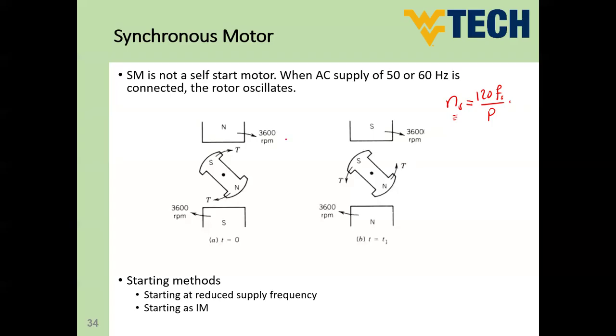If you imagine with me now in this figure, I'm going to assume that you have a pole when we supply the motor at one time, let's say at t equals 0. The pole on this side is N and on that side is S. And with time, this pair of poles will start rotating.